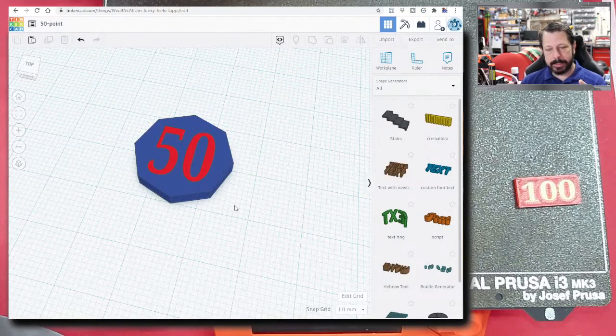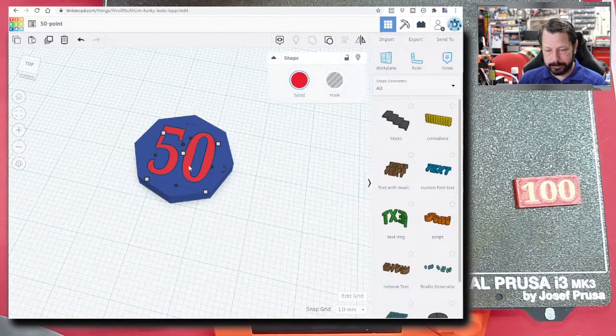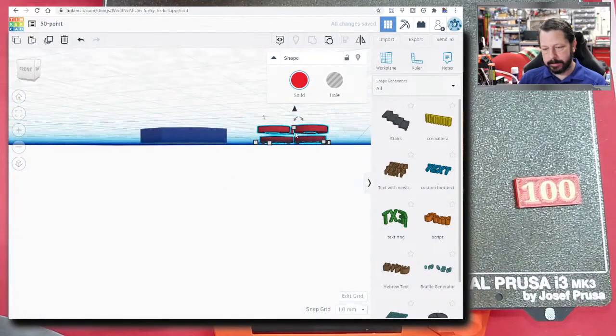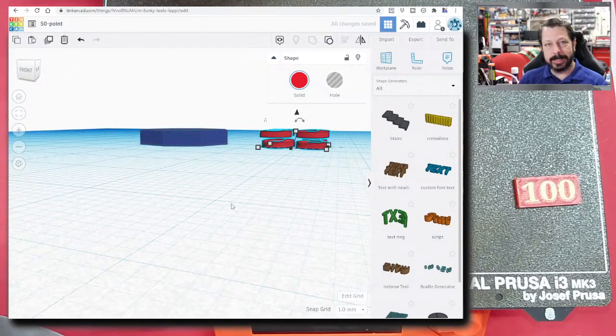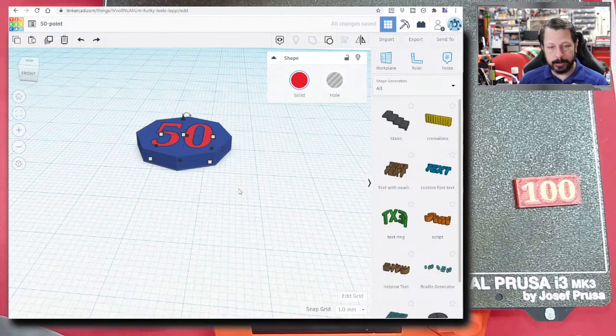And now what will happen is, since you've lined them up and cut away the hole that the others go in, you can print. Now this particular one would not work without a multi-material printer. These are intended to be printed simultaneously. You couldn't print this, right? Because it's floating above it. You'd have to actually connect those together, or print them separately so you can insert them later. But this is how you would do it if you were going to print it as a multi-material part.